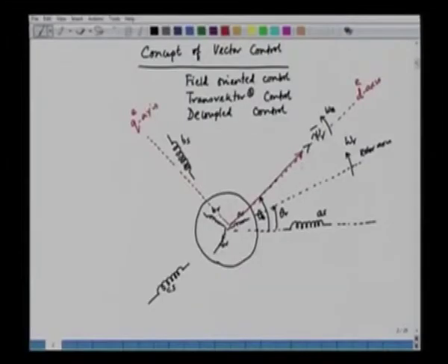And when we are analyzing this from a rotating reference frame, we can always have fictitious windings like the dS winding and qS winding. So we can have the stator windings which are fictitious. So we can have the windings here in the stator, and this you can call to be dS winding, but this is rotating with the rotor flux vector. So we can call this ds superscript e. And similarly, we can have a qS winding, and the qS winding is also a rotating winding.